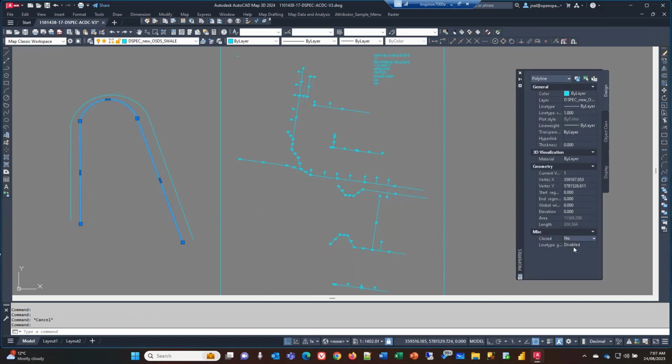Now, one of the things with standard AutoCAD is I can do a polygon, but what if I've got a park area or a road, and I've got a roundabout inside that particular road polygon? How do we handle that? Standard AutoCAD cannot do that, and that is where AutoCAD Map then comes in. I'll go into a little bit more detail on that, but where I'm coming from: here you have lines and arcs to a polyline, but then we can also construct a multi-polygon, which is once again built on top of a polyline.